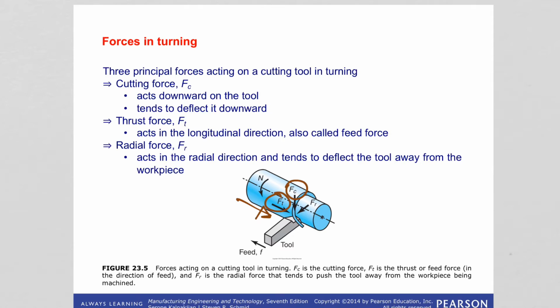These forces are difficult to calculate directly because a variety of factors affect the process. Therefore, these forces are calculated experimentally. Why are these forces important? Because the machine tools and their components should be able to withstand these forces without undergoing significant deflections, vibrations, and chatter.